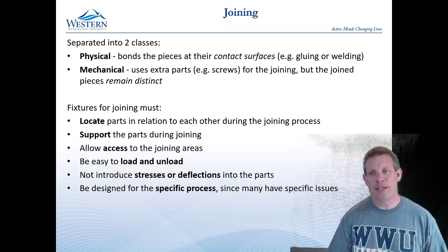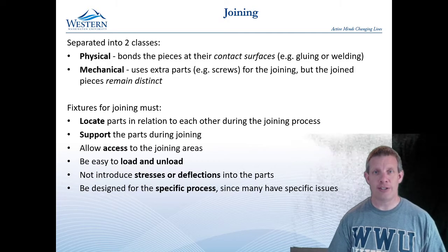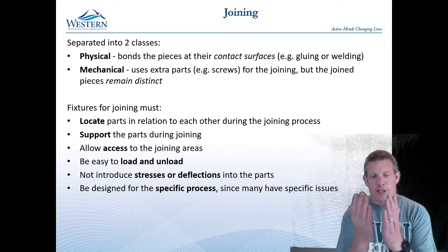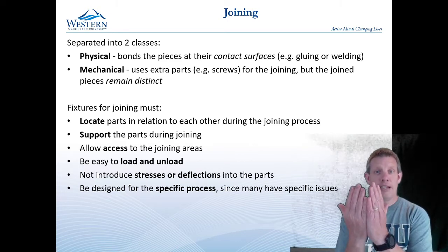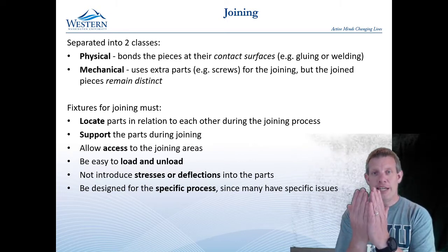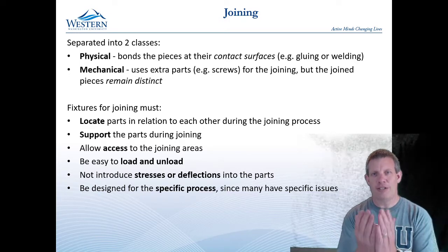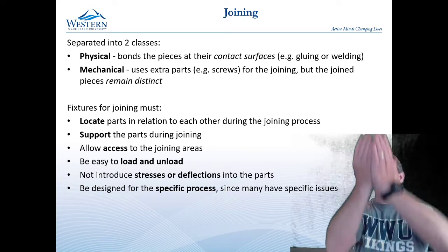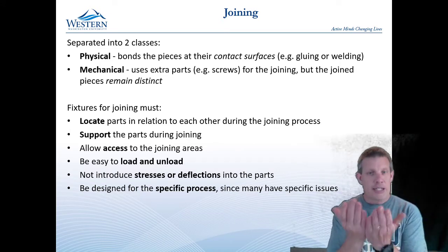Online, and one of the things that you're going to find is that loading and unloading the fixture is by far one of the hardest things to do. Because if you think of a fixture that holds these two parts together really well, and if these are big parts and you hold them together really well, then while it was easy to take these two parts and slip them in, now to get them out, either one part of the fixture has to collapse, or you have to lift the whole thing out of the top or slide it out, and now it's this big structure.